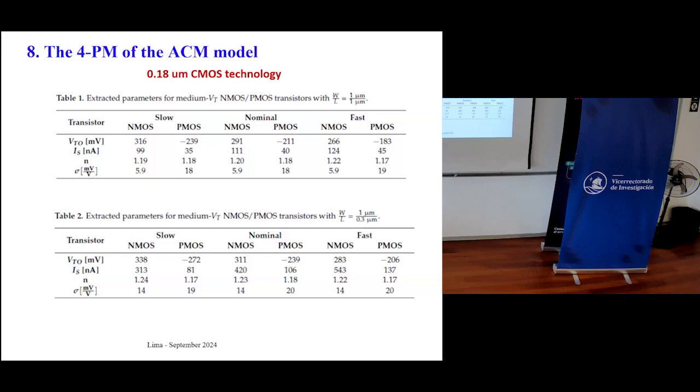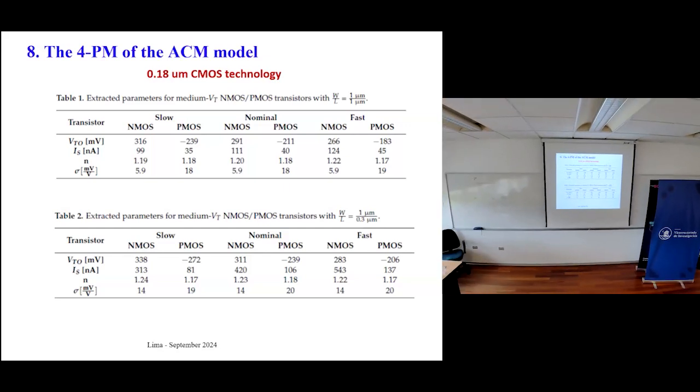And the EDA tool will indicate where is the problem and what should I do. Then, you have not respected the distance rule, so increase the distance. So you have lots of rules, and you don't have to know all of them by heart, but you have programs that will help you during the design of your circuits.